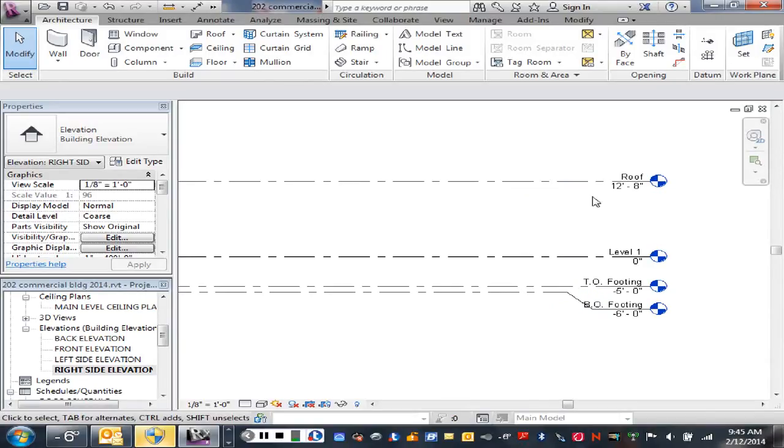Let's see how that would work backwards to come up with a ceiling height. So what kinds of things on this type of building do we have to take into account as far as how much lower would the ceiling be than that? So it's a masonry building with a flat roof, right? And when you look at flat roof buildings around, you don't see the roof at all, right? Because the roof is actually lower than the top of the wall. There's what's called a parapet, right? Everybody knows what a parapet is? It's when the exterior wall extends above the roof.